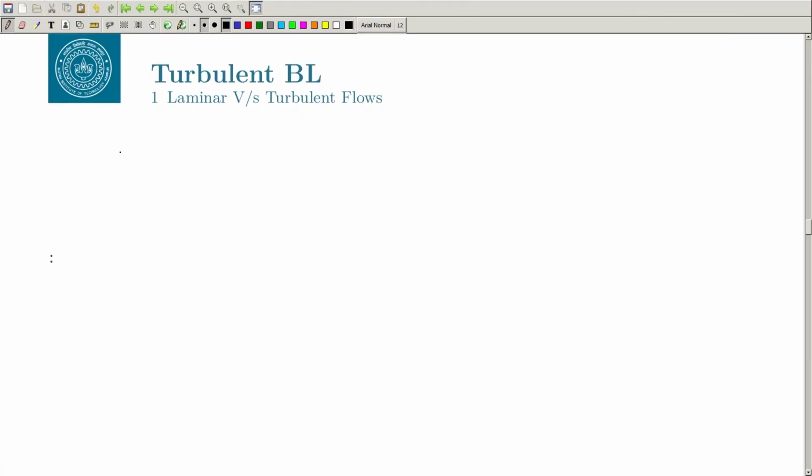The laminar boundary layer, you can talk about, let us say, the Blasius boundary layer if there is no pressure gradient, or you can talk about the Falkner-Skan boundary layer, and you can represent the laminar boundary layer easily. For the turbulent flow case, we discussed that there are several layers. First we can broadly classify into the inner layer and the outer layer, and within the inner layer you have several layers. So let us look at those layers and how we get the laws for those layers in today's class.